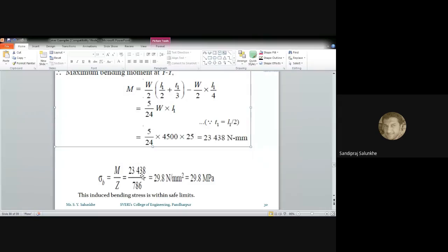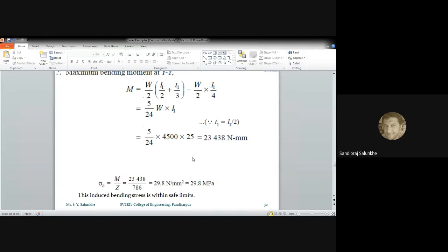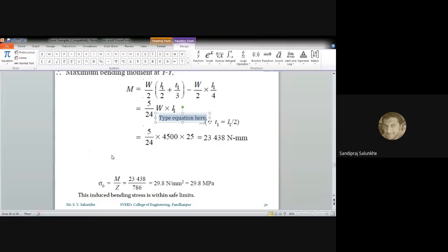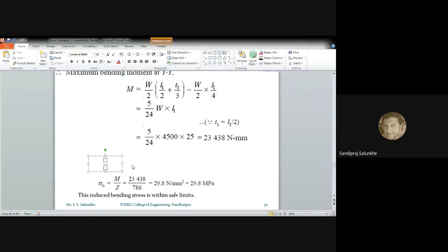Now here I have written directly the answer, that is sigma b. But how is this sigma b coming? So we are going to use the equation. What is the equation for calculating bending stress from bending moment? Can anybody tell me that equation? M by I is equal to sigma upon Y, sir. Yes, M by I is equal to sigma upon Y. So the I which you are going to consider...